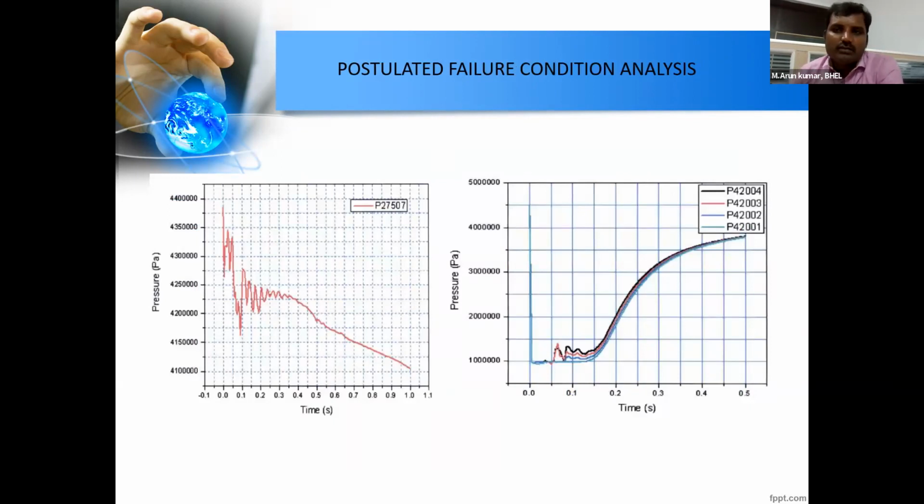Not only that, we have to foresee the force-related failure conditions. For example, if we are designing a heat exchanger or pressure vessel, in case of a heat exchanger, what happens if the outlet line breaks? Outside this line, only atmospheric pressure will be there. Inside, the pressure will be very high. The safety systems may respond within 3 seconds.